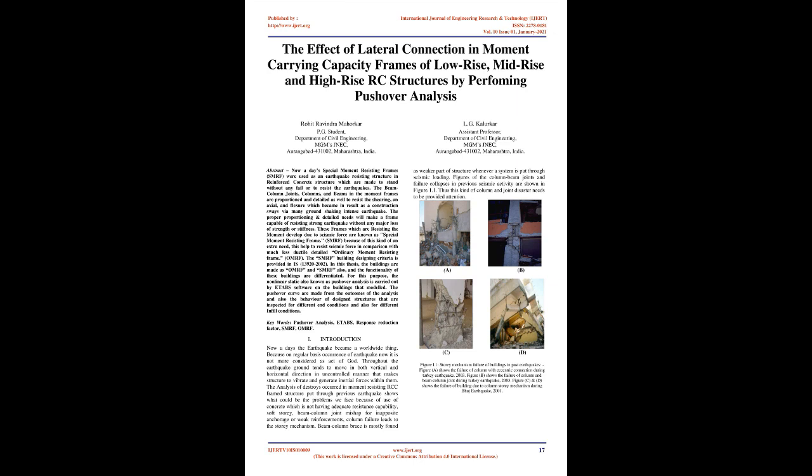The beam column joints, columns, and beams in the moment frames are proportioned and detailed to resist the shear, axial, and flexure forces which result as a construction sways during many intense ground shaking earthquakes. The proper proportioning and detailing will make a frame capable of resisting strong earthquakes without any major loss of strength or stiffness. These frames which resist the moment developed due to seismic force are known as special moment